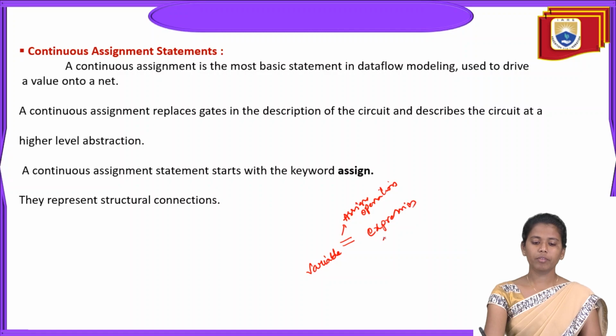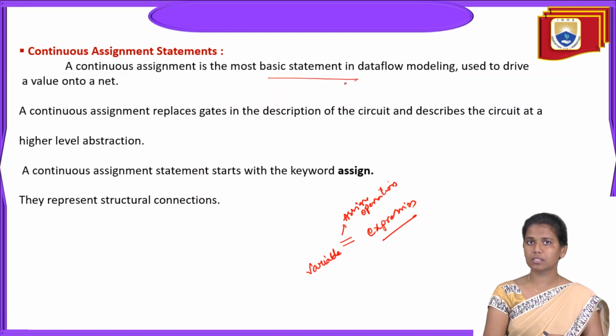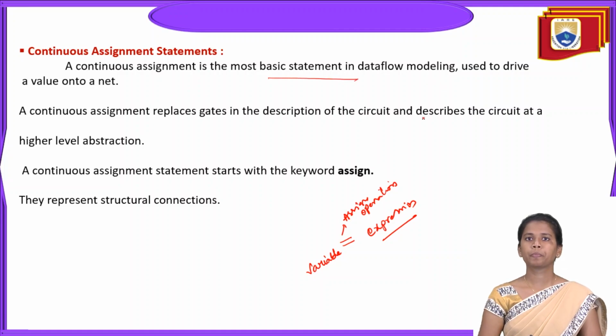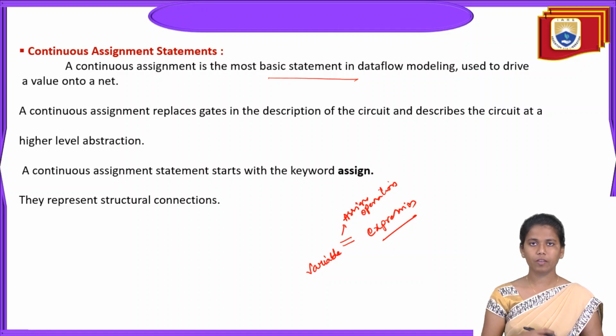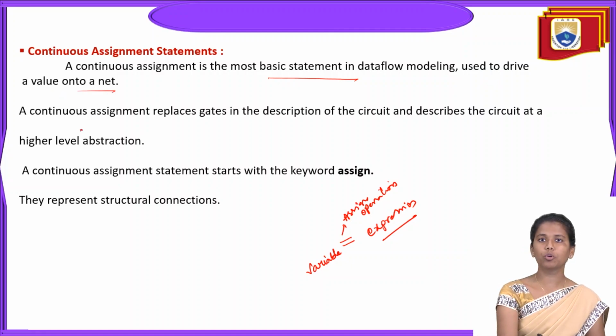Continuous assignment statements are the most basic statement in data flow modeling. In data flow modeling, all our statements are basically in the form of continuous assignment statements, and the execution or the synthesis of these statements goes synchronously. They are used to drive a value onto a net.